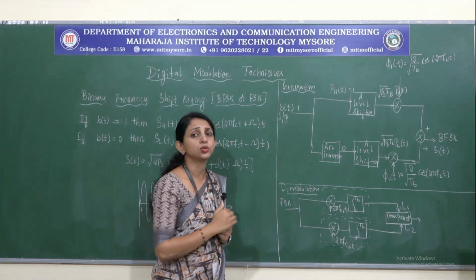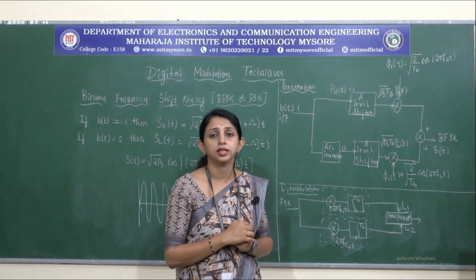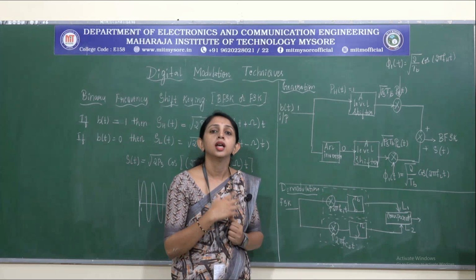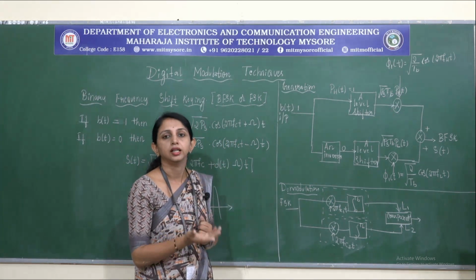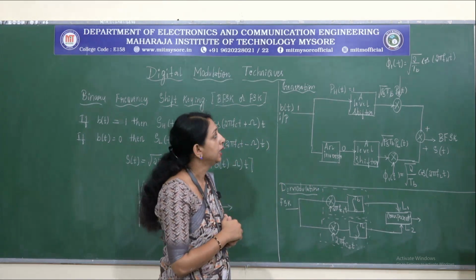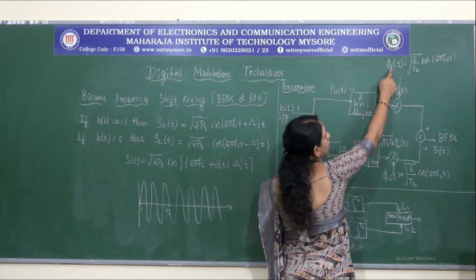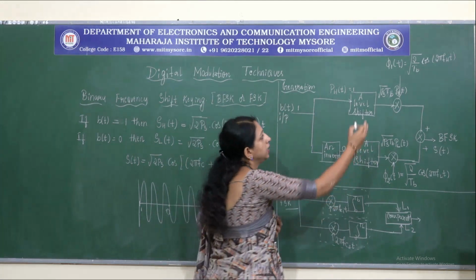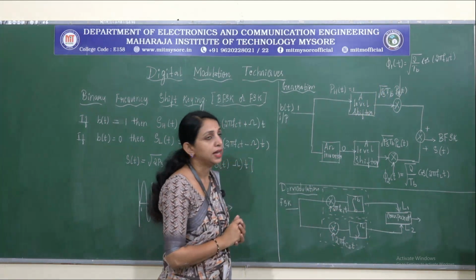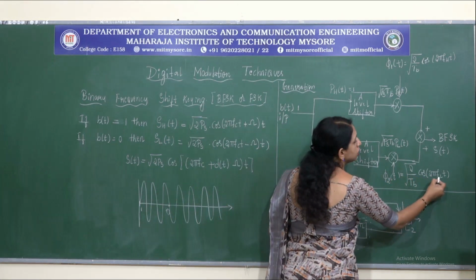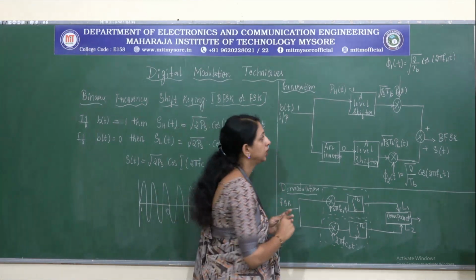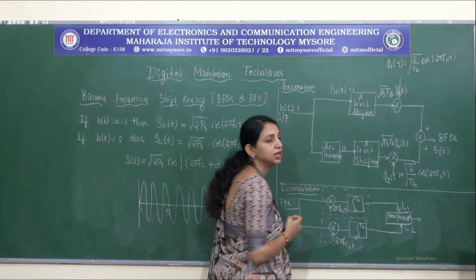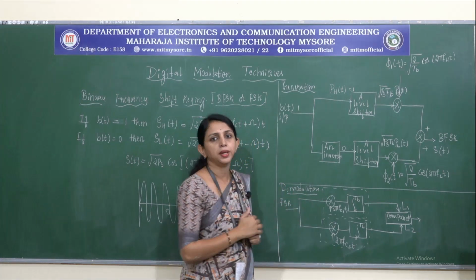So now these two signals should be multiplied with the product modulator along with the carrier. Of course, at both the transmitter and the receiver ends, we require a carrier signal. So take that carrier signal from the oscillator, which has the form cos 2 pi fct. Let us take the high value as phi 1 and the low value as phi 2. So high is represented with cos 2 pi fht and the low signal is represented with cos 2 pi flt. Here in both cases, the levels will be the same. The level remains the same value, square root of Ps into Tb, for a high value. If it is 0, it will be 0 itself.